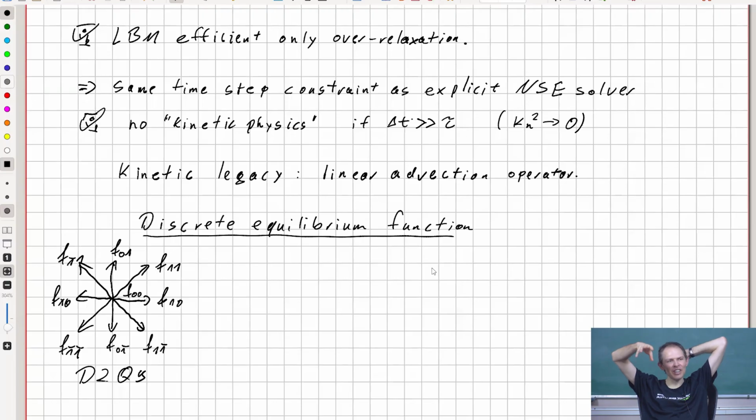The diffusion in the Lattice-Boltzmann method and in the Boltzmann equation itself is nonlinear, whereas the advection is linear. Now you derive the Navier-Stokes equation, and what comes out is that the diffusion is linear and the advection is nonlinear. Please explain how this came to be. I don't know, but this is the result. So Boltzmann equation: diffusion nonlinear, advection linear. Navier-Stokes equation: advection nonlinear, diffusion linear.